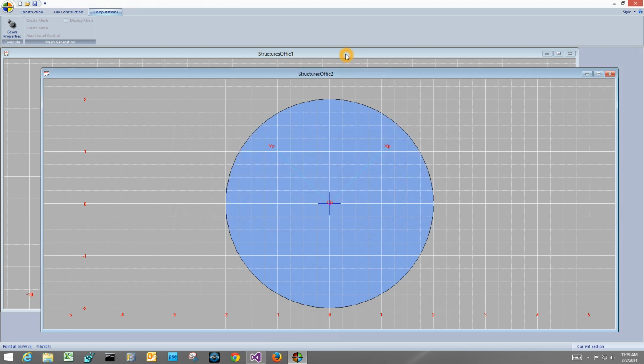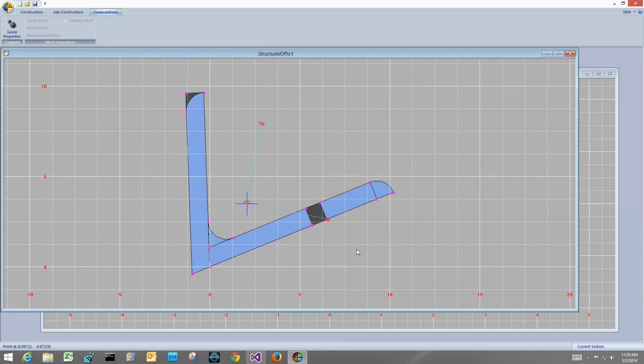Just keep that in mind, that your active document is where it's happening. So if you do a save, it's saving this section, not this section. It doesn't do both, it only does one at a time. So just be aware of that. Whatever is on top is active, that's what these functions apply to.